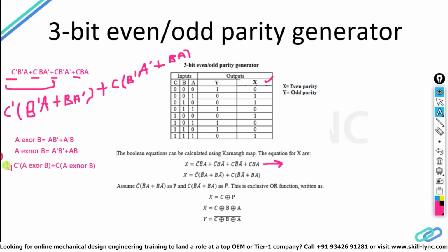So what I did, I have just written down the equivalent logic gates here, because otherwise you have to take B, then you have to take B bar, then you will take A, then put a NOT gate here, then you will take an AND gate here, then put an OR gate here. But instead we can just take two wires A, B and put an exclusive OR gate and take the common term out. Now understand one more thing, that it is A XOR B complement.